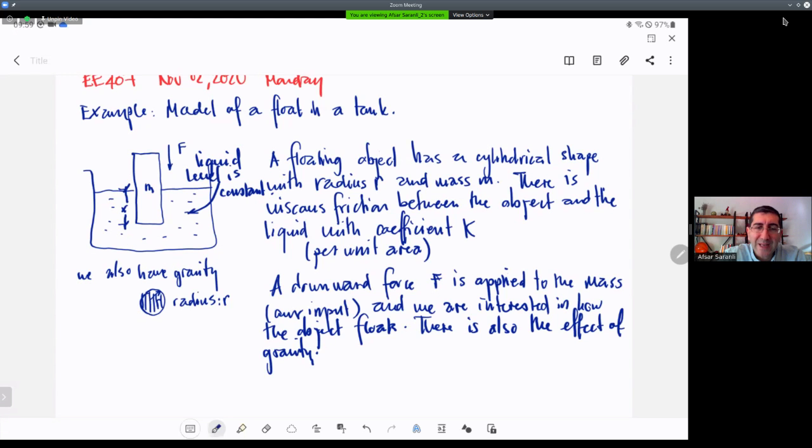So in reality, the direction of the actual current, for example, can be in the reverse direction of what you have assumed to be the positive direction. So making assumptions on the direction does not mean that those variables will always have the same sign. You make an assumption on the direction, and then you determine when that variable is positive and when it's negative, because often those variables are also time varying. So they will take positive values and they will take negative values.